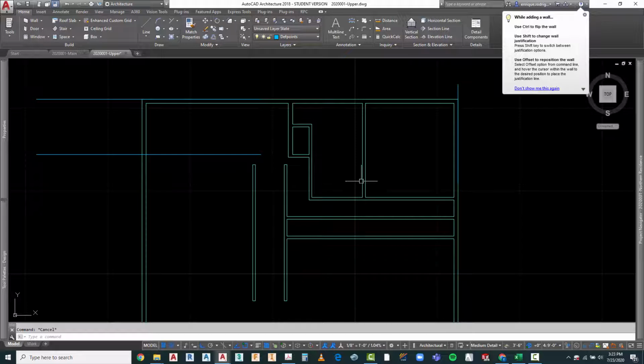And it's giving me a distance from this side of this wall of 3 foot 5 1/2 and another 1 foot 9 1/2. So let's go ahead and round that off to 1'10" and 3'6". So I'm going to go ahead and, just using line work rather than anything else, copy this over. First I'm going to go to 3'6" that they're telling me, and then I'm going to go ahead and, in this case, I'm just going to do another.